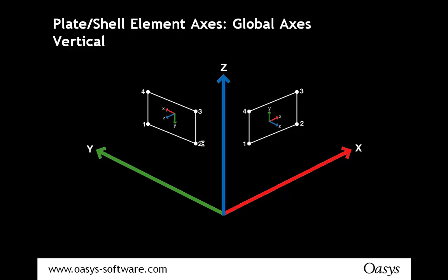If you're just doing general analysis, it's not too crucial, but if you're doing the reinforcement design with 2D elements, it is totally essential to have good control over where the element axes are going. Otherwise, your design aspects will be nonsense.